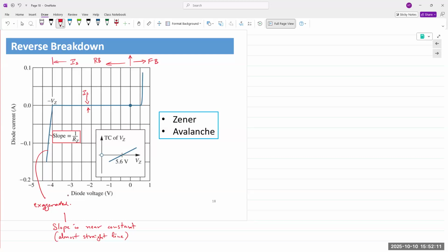And then there's a sudden influx of these charge carriers, and they all cross over the junction because of the applied electric field. This is known as impact ionization. Electrons are impacting the atoms, creating more ionized atoms. More charge carriers are generated. They result in more energy being fed from the electric field. And thus, it results in an avalanche of charge carriers crossing through the junction. And that is known as the avalanche effect.